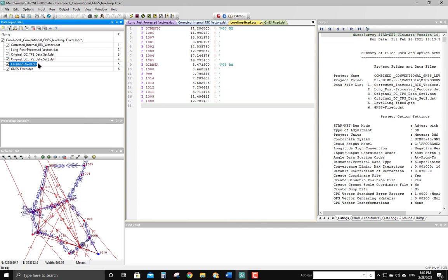And an option was turned on to just make them output as fixed elevation records. And so these final elevations are in essence being input as a constrained elevation for the stations that the other types of observations touch onto. And this is an ability StarNet has that I notice makes a lot of people smile. It does solve a lot of problems.